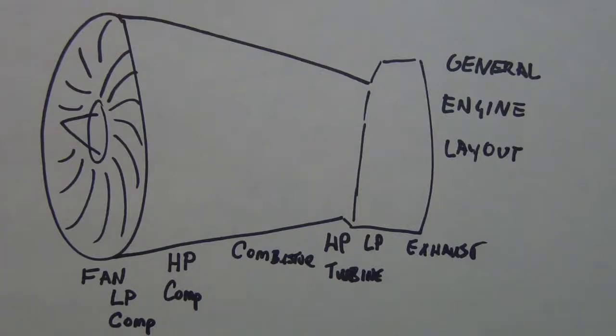Bottom line is, anytime you have something moving, especially when you're talking about main engine bearings, what's the most important thing you need to be conscious about? I hope it starts with the letter L. It's lubrication, right? Lubrication is so important. So keep that in mind, lubrication when you have engine bearings. The distribution of engine oil is all going towards the lubrication of these bearings.